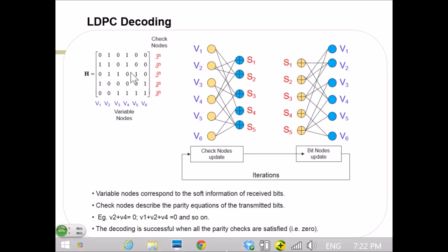I think one thing I would say, we never need to use, let me say one thing. We've done several encoders and several decoders. You don't need a generator matrix to do the encoding. You can do the encoding using the H matrix itself. So there is no real need of the generator matrix. But I don't know the code yet, because I don't know how many bits I get to put in and how many parities. No, I think you are missing the definition of the H matrix. The H matrix is defined such that the rate of the code, you can say that the number of bits...